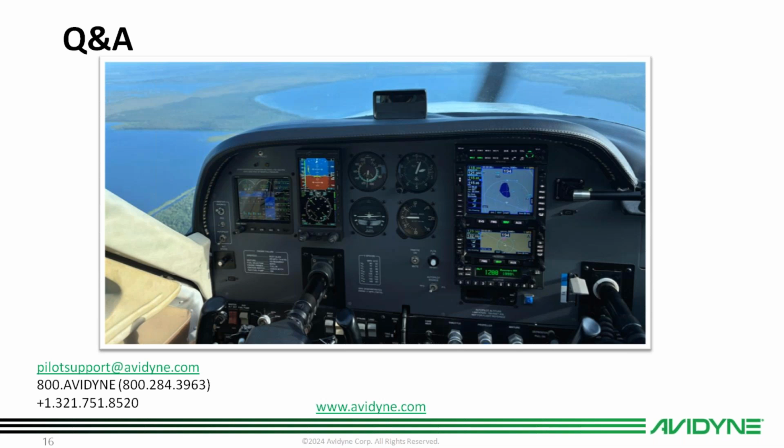Thanks, Will. Yes, sir. I have a 2002 G1 SR22 with Garmin 430Ws. Will it be a plug and play install for me with two IFD 440s? Yes. It depends on the transponder, of course. If you have a GTX 345, there's that one change that we talked about, but any other transponder is pretty straightforward.